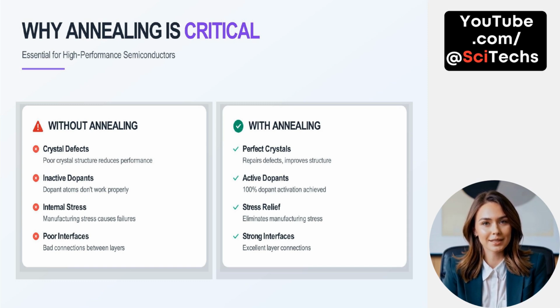In contrast, annealing solves all of these problems. It creates perfect crystals by repairing defects and improving atomic structure. It ensures active dopants, with 100% activation rates often achieved. It provides critical stress relief, eliminating stress introduced during fabrication. And finally, it results in strong interfaces with excellent layer-to-layer connections. Altogether, annealing is not optional. It is a foundational step in producing high-performance, reliable semiconductor components.